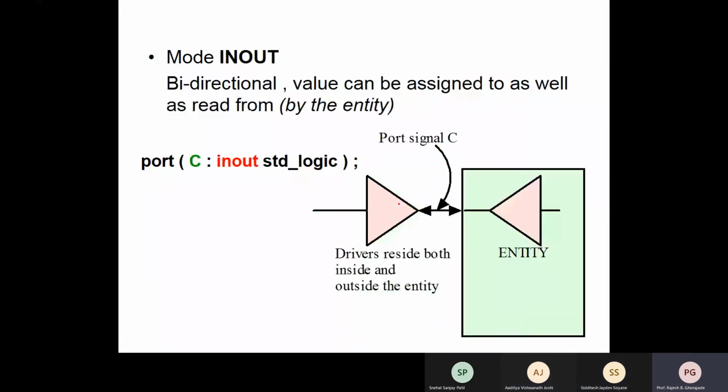In a similar way, we have mode inout. Now, this is a special type of port where you have drivers residing both inside and outside the entity. Naturally, the value can be assigned to as well as read from the entity. It does not mean that you have to use it frequently. We'll see what is the problem with that.